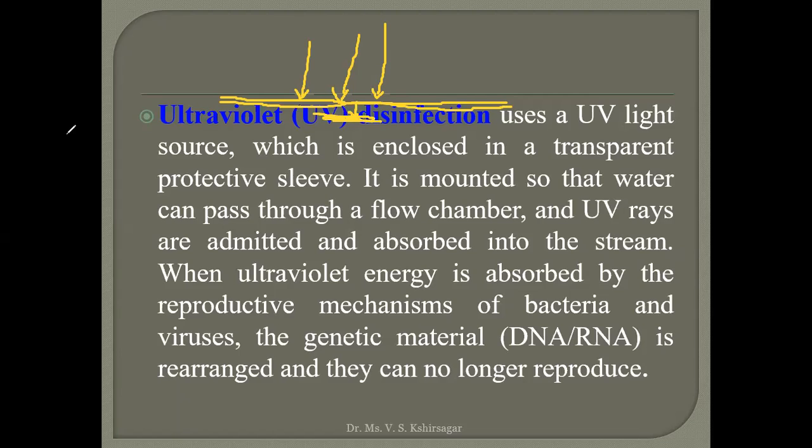Okay. So as the passage is longer, water age will be longer. As the water age is longer, there is more possibility of recontamination. So as per the water age, we need to take care of recontamination in such a way that it will not get recontaminated.